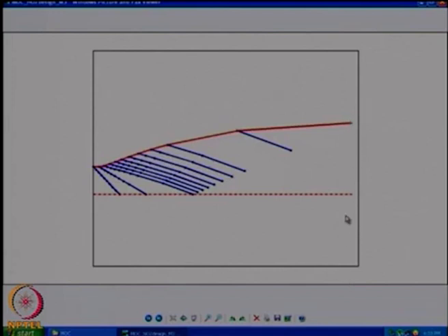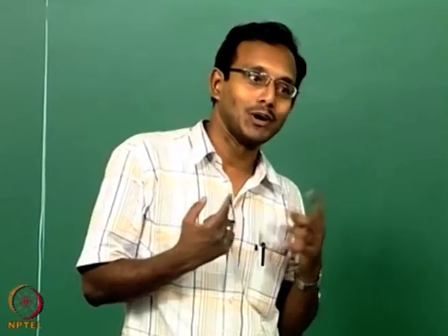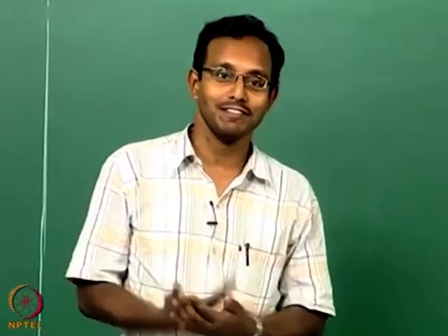So if I now make a nozzle with this particular red line profile, I will get uniform flow with exit Mach number 3. Of course, I checked by giving the same surface to a method of characteristics code, and I got the exit Mach number to be 3.05 for this particular case. So it is not exact, which means I have to have more points on this expanding wall to be exact. I did not do that in this case, so it is just 3.05, a small error. I am ready to live with that. And I would say one more thing, typically if you are designing something by purely inviscid analysis, this method of characteristics is purely inviscid analysis.